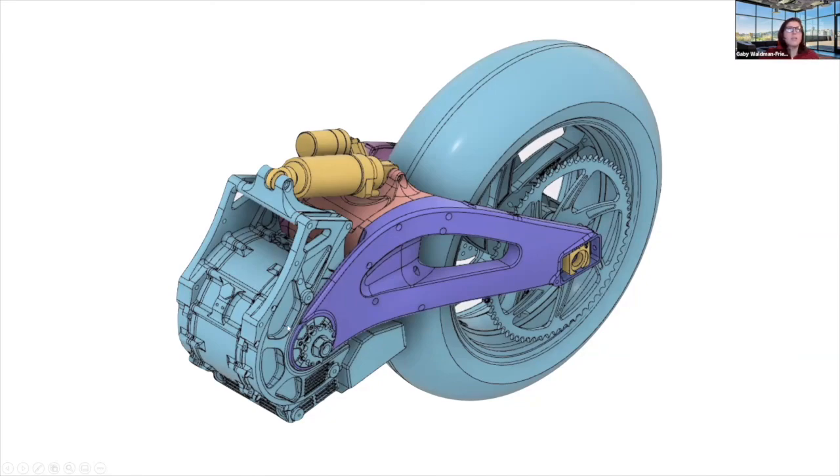So when they went to run this through generative and create this new swing arm, the first thing they had to do was set up the geometry for generative design, which identified two types of areas. One is called preserves, and that's what you're getting at with boundary conditions, right? Preserves represent the areas that you need to preserve as is, that you want in your final generative model, but you want them preserved as they are. So in this example, these are the preserves.